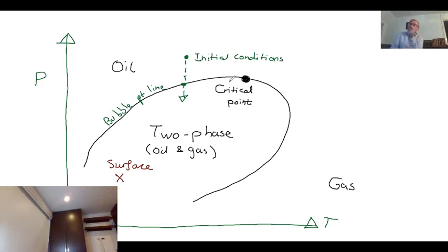And the first droplets of gas that come out tend to be more and more, one might say, oil-like. And at the critical point is actually technically when you switch from producing bubbles of gas to droplets of oil. So exactly at the critical point, when you produce the two phases, they are identical.